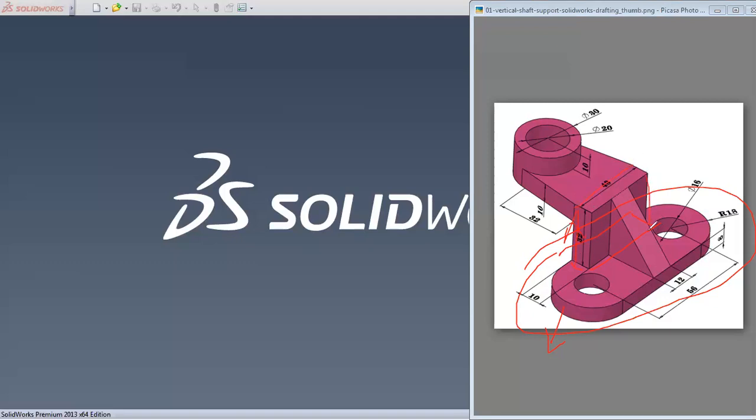Once this much is completed, I will draw this rib on this plane and extrude it on both sides. I will draw the rib at the middle plane and extrude it both sides. So this will be my number one, this part will be number two, and this rib will be number three. Okay, let me clear it. So this much has been drawn.